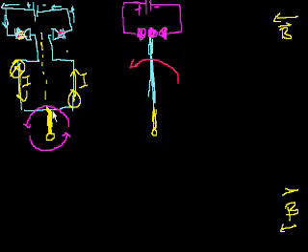So going back to our first video, we have the current going down like this. And then if you use your right-hand rule with the cross product, you know that the net force from the magnetic field is going to be downwards on the left-hand side, upward on the right-hand side. So you have a net torque rotating it like that, rotating the right out of the page, the left into the page or into the video screen, up to the point that you've rotated 90 degrees, and now you're looking